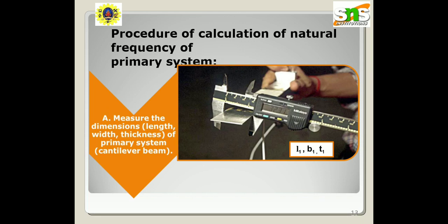excitation frequency. Given a motor with a mass M1 attached via motor mounts to the ground, the motor vibrates as it operates, and the soft motor mounts act as a parallel spring damper K1 and C1. The graph shows the effect of a tuned mass damper on a simple spring mass damper system excited by a vibration with an amplitude of a unit of force applied to the main mass.